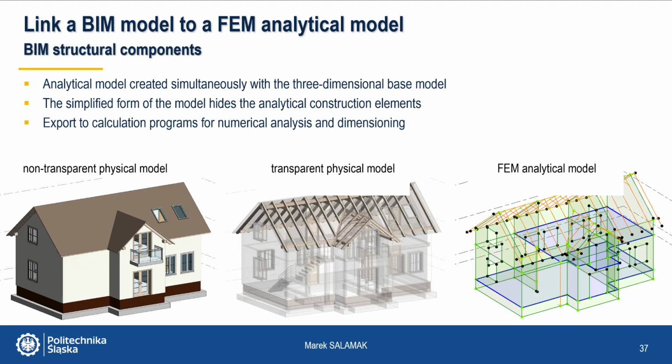The finite element model, analytical model, can also be associated with the BIM model. In many BIM programs, the analytical model is created simultaneously with a three-dimensional basic physical model. Usually, however, the simplified form of the model hides non-structural elements.